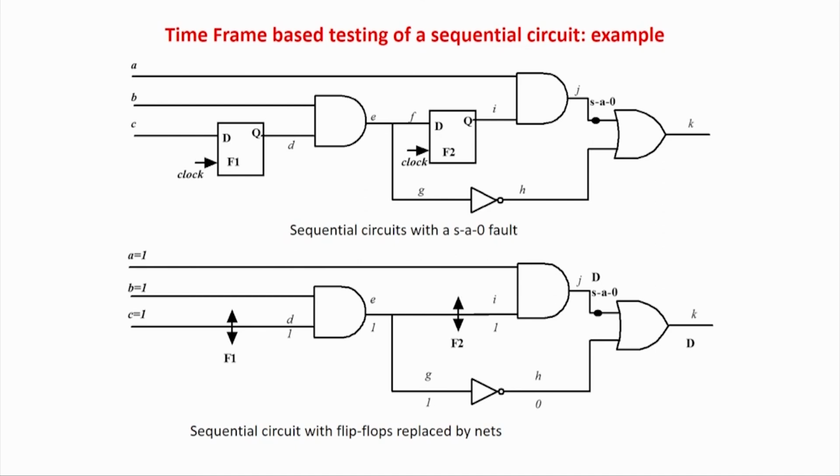So you require test patterns and 10,000 clock pulses to set it, and in the case of scan it is the same story. So generally, scan chains may not directly help you solve the test pattern application time. They only help to minimize the time required to generate the test patterns.